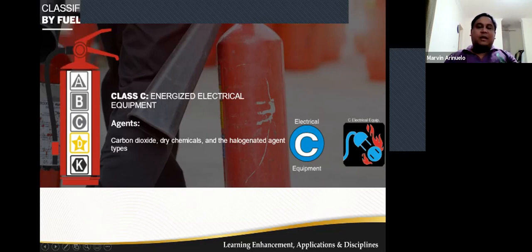Other combustible metals may require manually applied agent, for example sand. Sand, especially in Qatar, is available everywhere. Also, I've seen this available in many sites, especially near the smoking area.